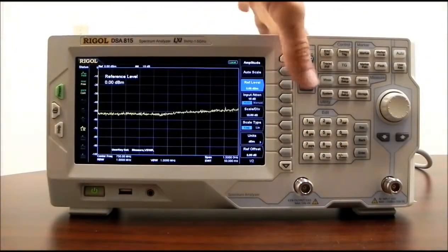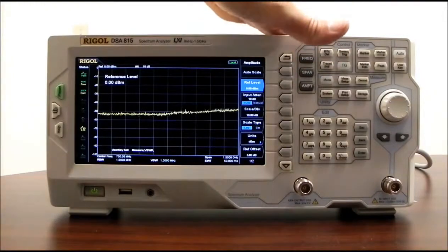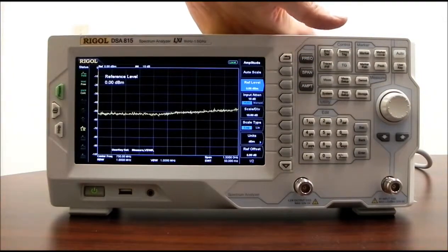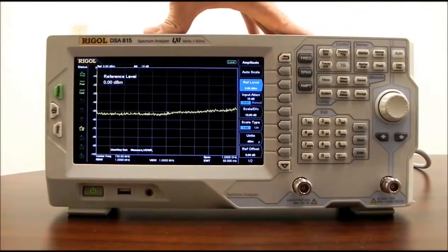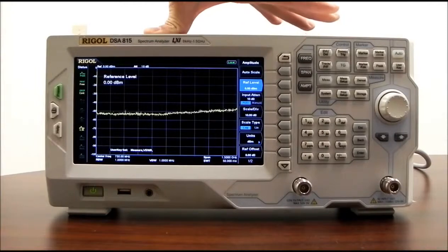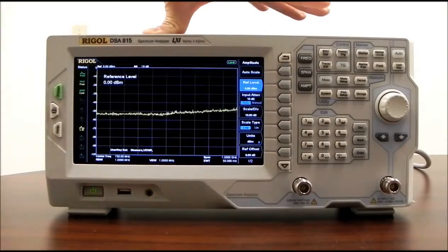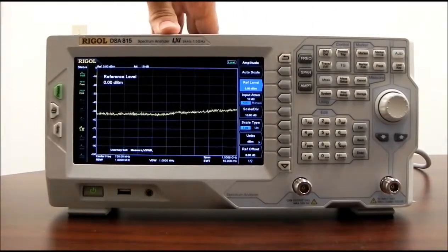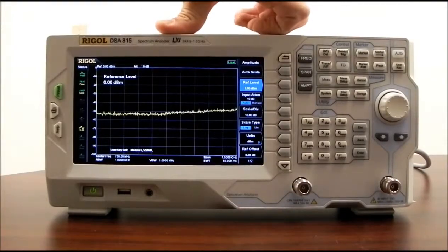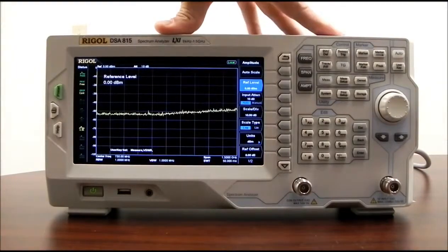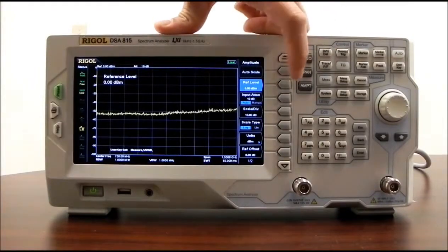And then input attenuator. The DSA 815 has an input attenuator that, as in factory defaults, automatically comes up as 10 dB. The idea is that we're going to attenuate that input just slightly, and it helps to protect the sensitive circuitry just in case you have any transients that may be discharged while you're connecting, or if you have a source that's connected that you're not entirely sure what that value is going to be. A good idea is to put in a level of attenuation in order to be able to protect that front end. Generally leave that on auto.